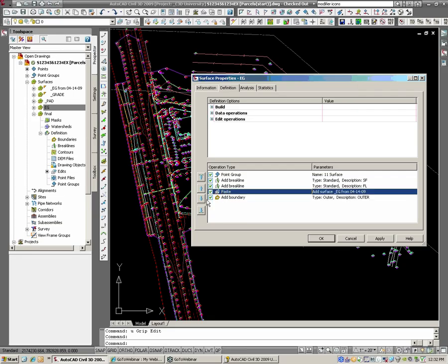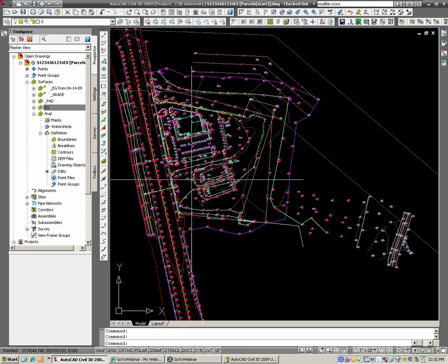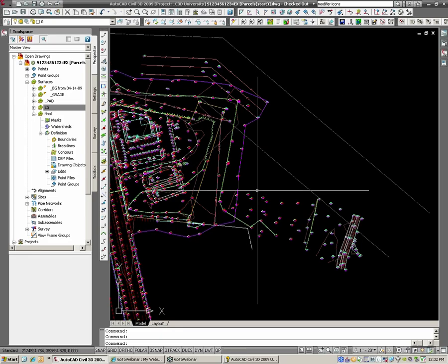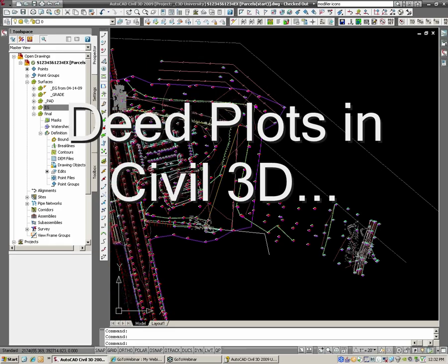If you want a gap, you don't want it to triangulate in between the space. If you have space in between your surface paste, you've got to make sure your paste is below your boundary. Okay, keep that kind of stuff in mind. That's the little tricky things of Civil 3D we all have to pick up. Okay, no more questions, I'm going to move on here.